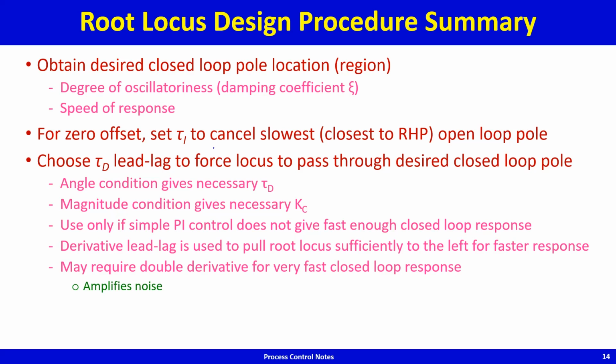If you want the response to be quickened to a very large degree, then a single derivative lead lag may not suffice, in which case you may have to use a double derivative. But please note that whenever you apply a lead lag where the numerator time constant is much larger than the denominator time constant, you actually end up amplifying noise. So that's the flip side of putting in these lead lags.